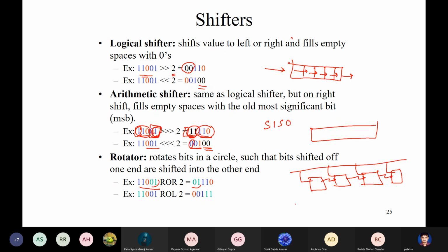If you tap these outputs and have a serial in, the input would just propagate along. So if you have 4 flip-flops, you have to wait for 4 cycles till the correct value is loaded in all the flip-flops, because your data is arriving 1 in each clock cycle. Then you can read out all the values in parallel.